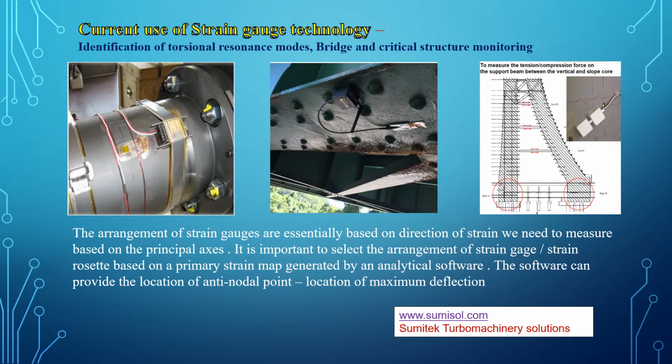So essentially combining all the above, my idea or proposal is to extend the role of strain gauges and strain gauge technology to detect and study the structural defects and anomalies occurring in turbo machinery or rotating equipment, thus using it as a tool to study their health.